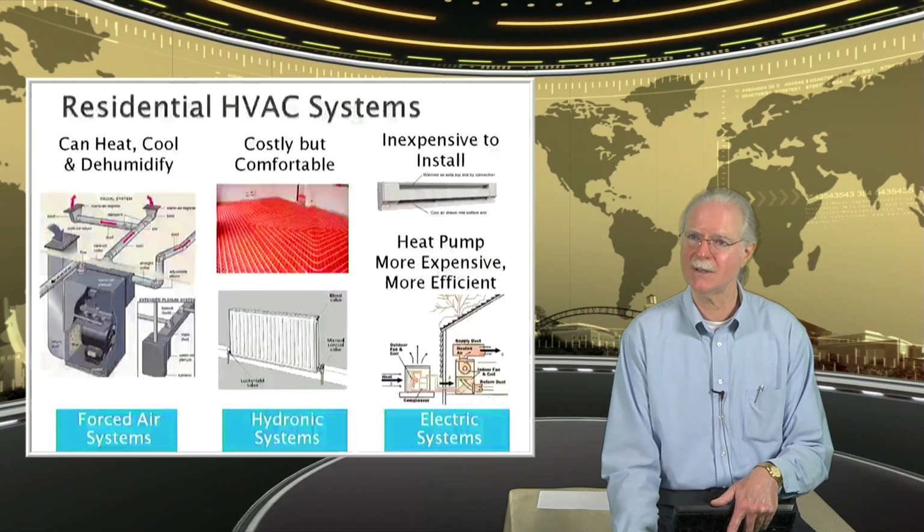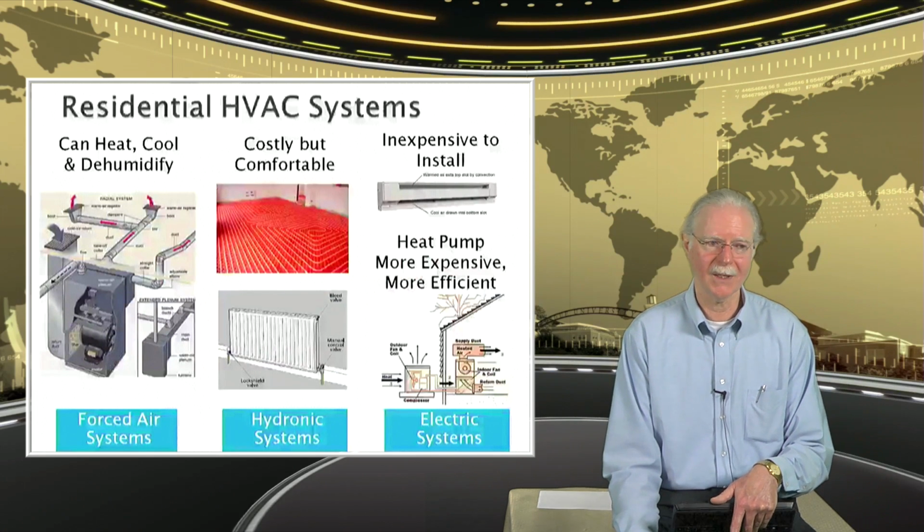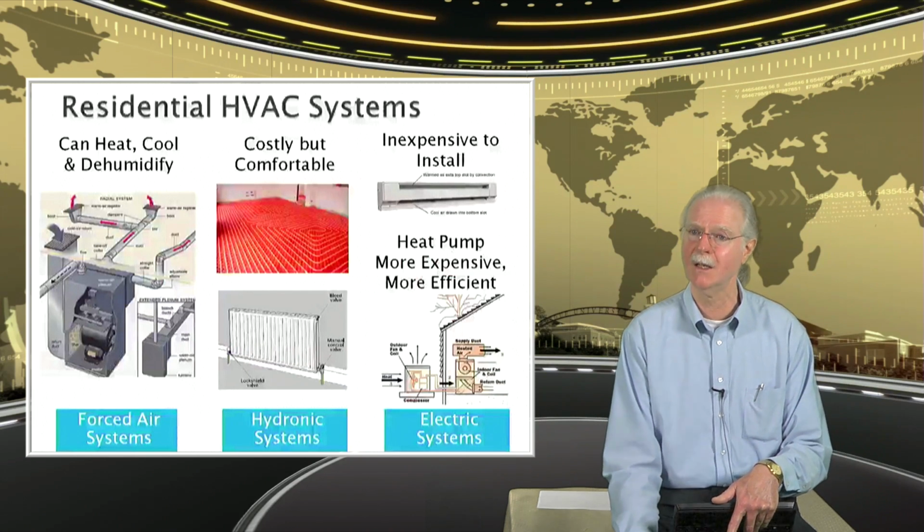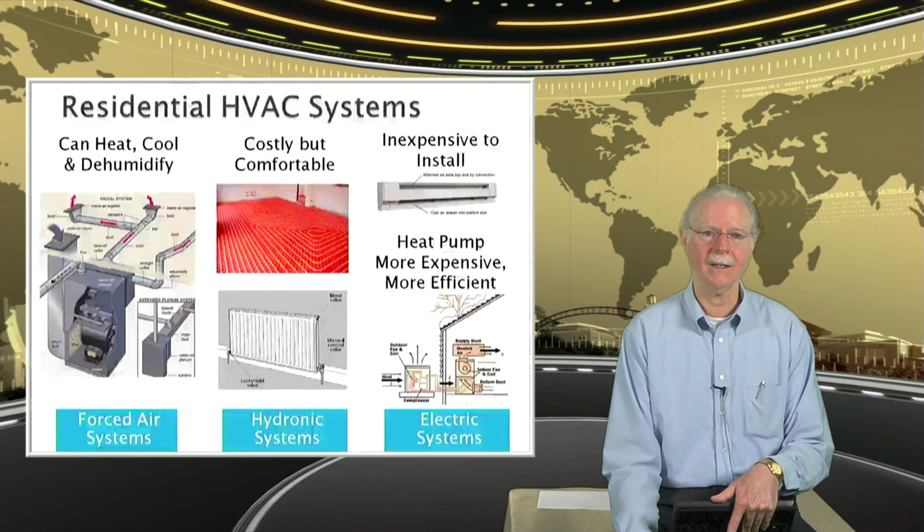These are more efficient systems. We can do things maybe 2 to 3 times more efficiently in terms of heating using a heat pump as opposed to electric resistance heat. So it is a common choice for heating, especially in the middle part of the United States.